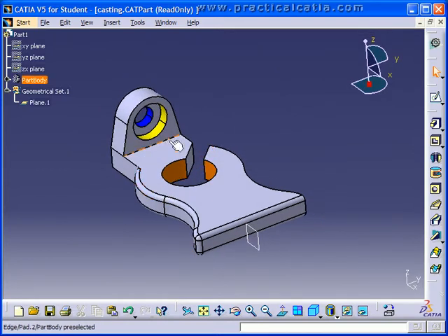One word of caution: while you're doing that kind of rotate with the mouse, where you're depressing the middle mouse button and the left or right mouse button, do not put your cursor over the part. If you choose the buttons in the wrong order, instead of doing a rotate, you'll do this duplicate, rotate transformation of the part, and the part will become messed up. So until you become really familiar with how the mouse buttons function, keep the cursor off the part.